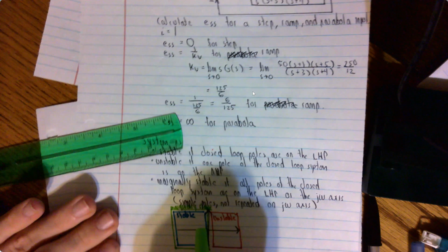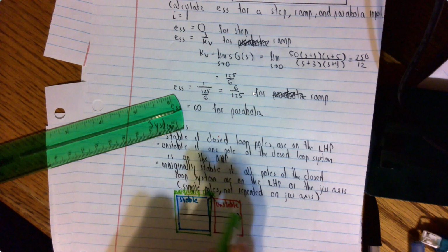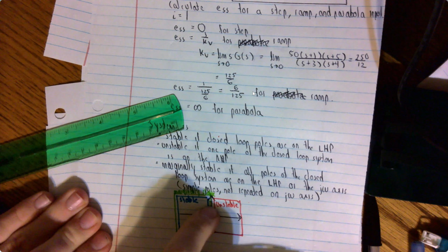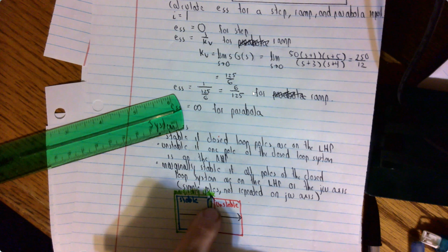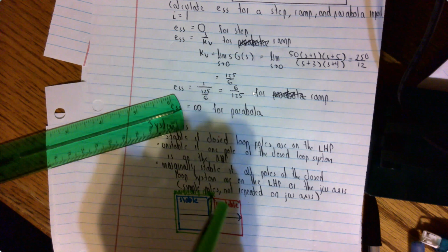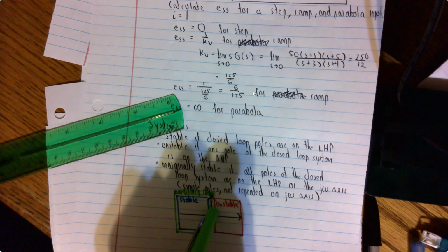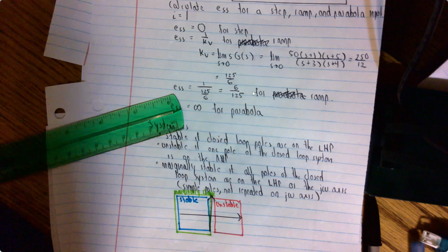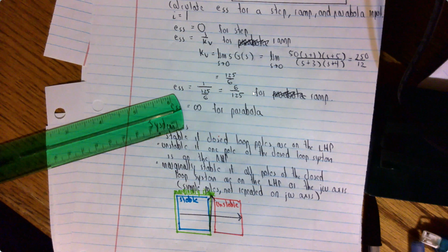So you can't have like two at the same point. If there's two right at like positive j2 here, if there's two poles on the j omega axis at the same point, then it is unstable. But it is marginally stable if there's only one. So say there's just one at j2, then you're fine. But you can't have two repeated there. And so what we're going to do is we're going to determine the stability of the following system.